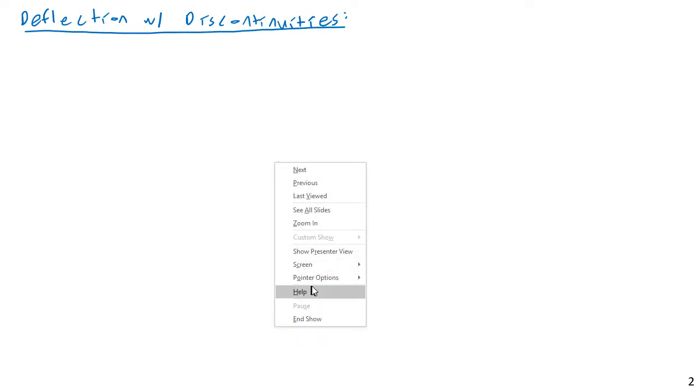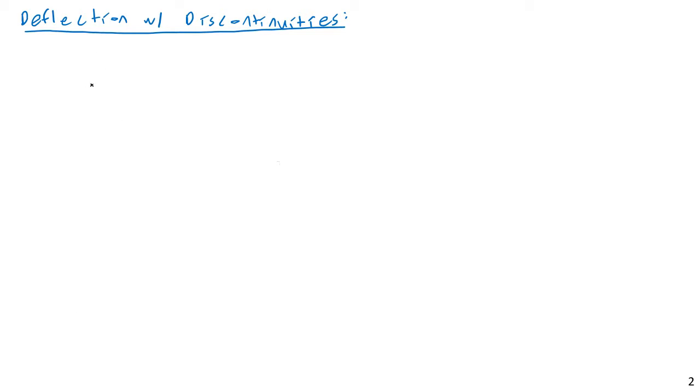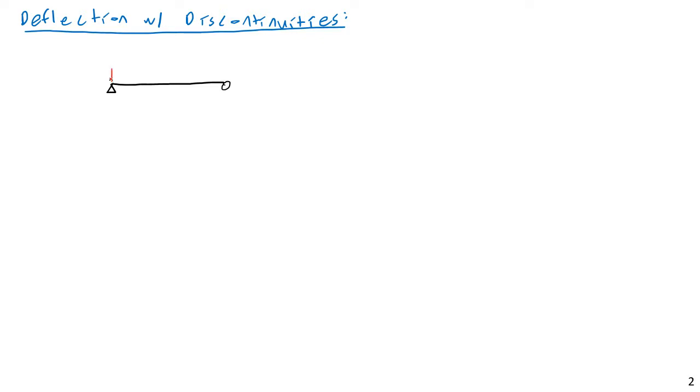So previously, we have looked at one or two examples of deflection, and this has always been with things that had no discontinuities in the loading. In other words, we had something like this. You might have a simply supported beam, for example, and some sort of varying, arbitrary load function, etc. But as long as this function is continuous, there are no discontinuities within the load function, and you can integrate it and find the deflection via one single zone of analysis.